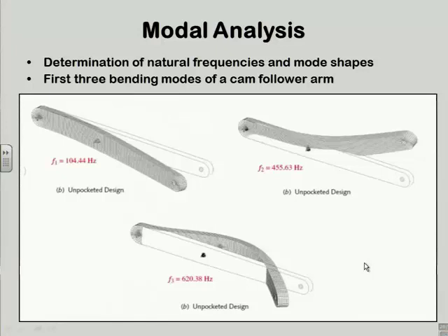And this is done more or less the same setup. Your boundary conditions have to be correct. Your mesh, well, in this case, you can have a sloppy mesh, because this is a deflection type characteristic, so it's global. And so having a coarse mesh doesn't make these numbers very inaccurate. So if I'm only after a modal analysis, I don't have to mesh the dickens out of the thing, because I'm not looking locally at stresses and so forth.